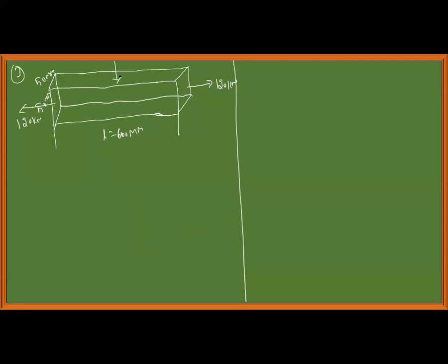Compression as he has given. This is a lateral dimension. Since this is the axial dimension, this is a lateral compression of 600 kilonewton. For equilibrium, there should also be load along this direction, 600 kilonewton. And since this is also a face of 50 into 600, this is also subjected to lateral compression of 600 kilonewton. That you should understand.